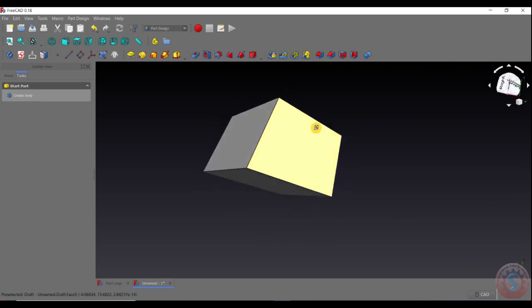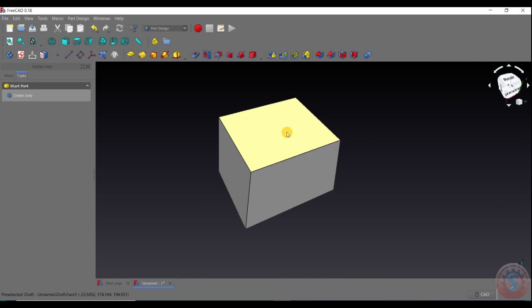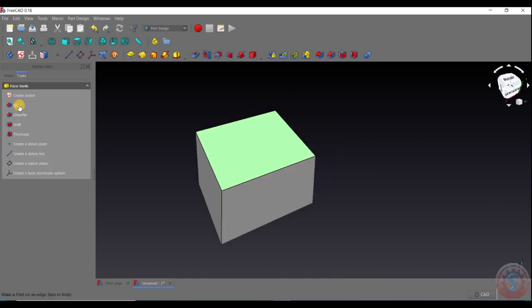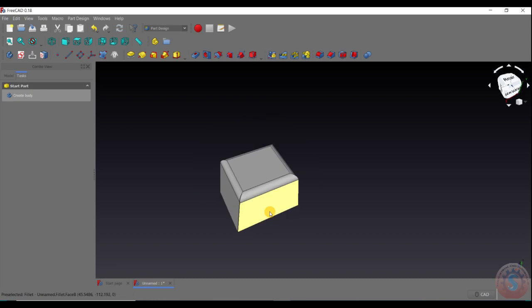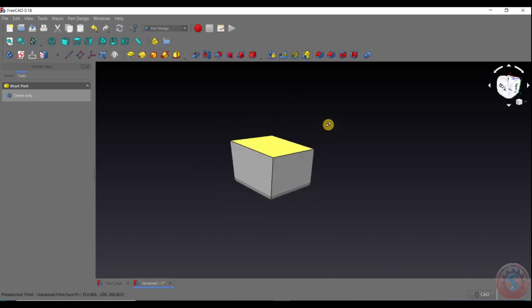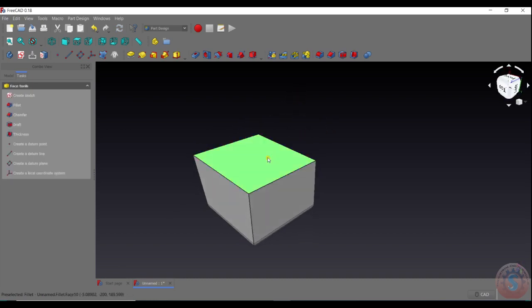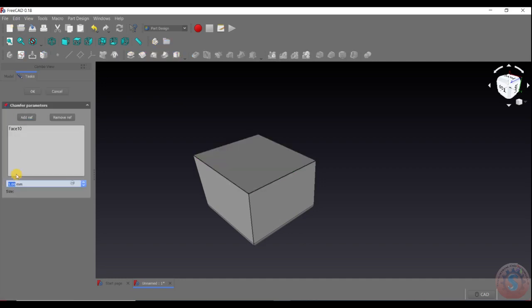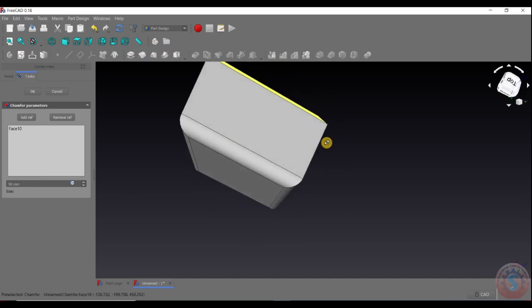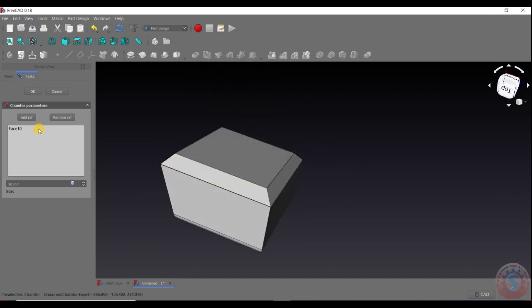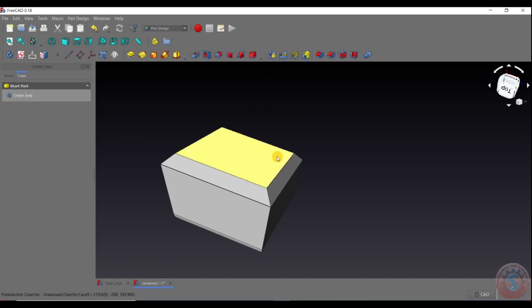And after that you want to give the fillet, select any of the face, and here you want to give, you can also give here. I am giving fillet to 50 and click on OK. And next, on the bottom side, I want to give the chamfer for explanation. Go into the chamfer. Here also I am giving 50. The chamfer is created, the fillet is created. Next you can observe the OK.